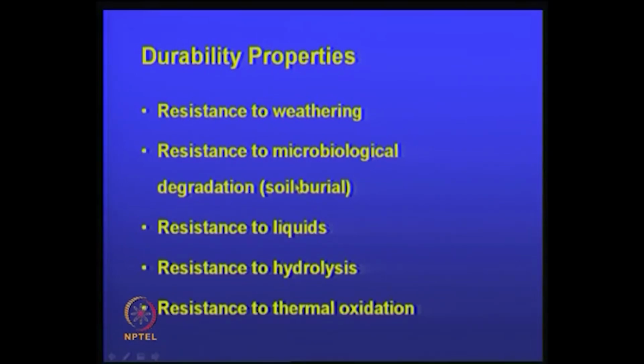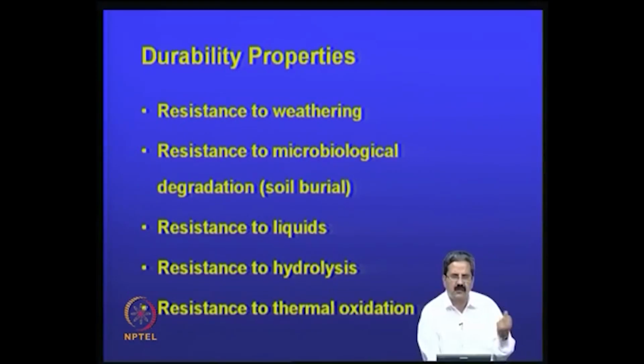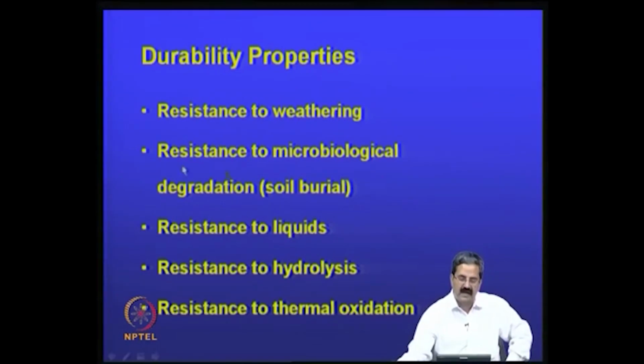Another important point that we should see is material durability. What you saw earlier: first we have seen how the material is identified, the second is mechanical properties, the third is hydraulic properties, and then the durability properties. Actually, we have also seen endurance properties, like the number of cycles it can go, abrasion tests and all that. After that, durability is another important issue that we should see, because if the geosynthetic materials do not last, say for example 30 years, then it is risky and you can't use them, because in our life cycle we are trying to design buildings for about 50 years.